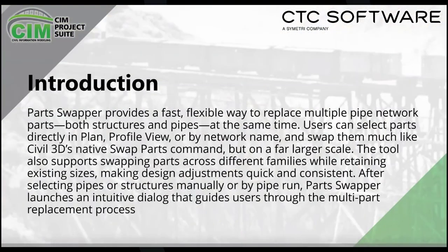So Part Swapper is really a simple tool that's meant to replace the native tool that Civil 3D provides, but we can do a lot more with it in that we can change our parts in plan, profile, or by network. And the tool will do this across different families as well and retain our existing sizes if you want to change part families within those. So after selecting them, we can run the swap and it will take care of all of the tools we have selected.